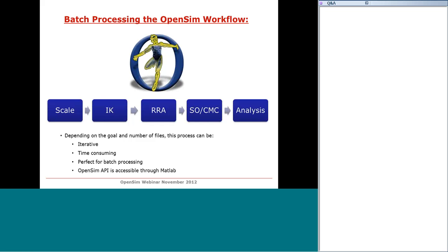It's now easier to run analyses, update model parameters, and populate fields within settings files. If designed correctly, a batch processing script can reduce user error and ensure that all subjects are processed in an identical fashion. In simulations where consistency matters, this may allow for more accurate comparison between groups. I've created a number of scripts in Matlab which can help to save time when analyzing many subjects. For example, one script populates all of the required fields in the settings files for a given subject and trial, and another runs each OpenSim process sequentially using the GUI and updating the settings file simultaneously along the way. And I'm going to make these files available on our project page.